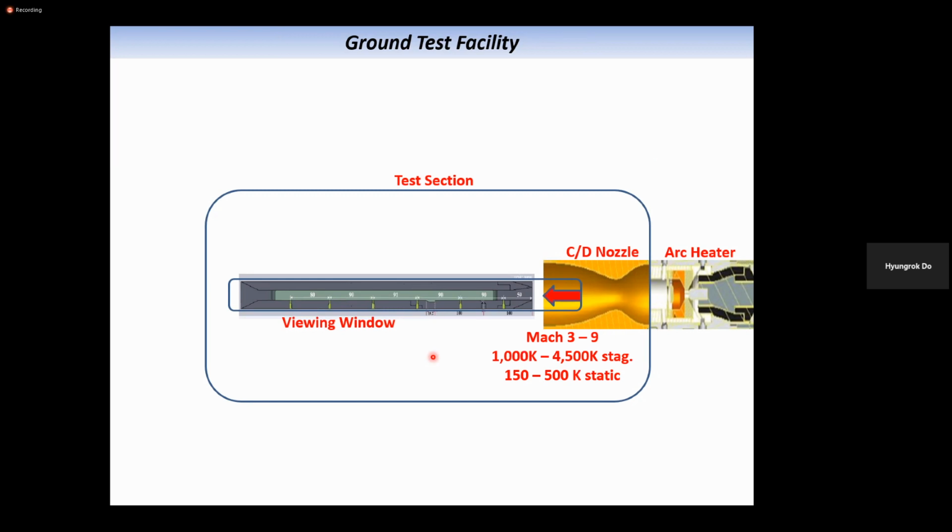Okay. So let's say your sensor is measuring some quantity for 1 millisecond. 1 millisecond means your gas has moved like 3 meters. The flow speed is 3,000 meters per second at least. For 1 second, 3,000 meters per second; for 1 millisecond, it is moving like 3 meters.